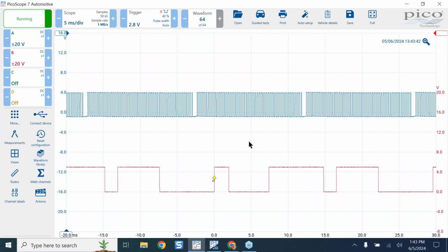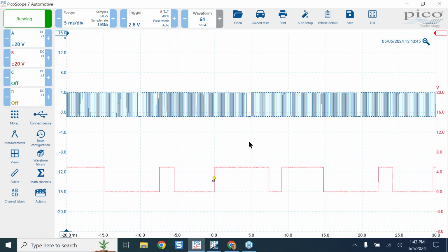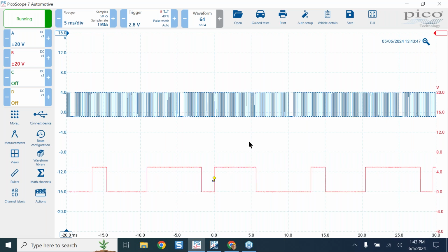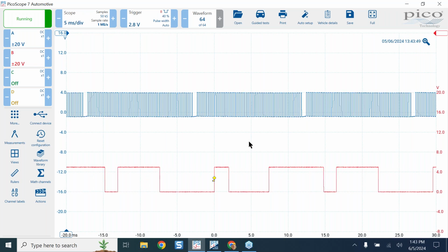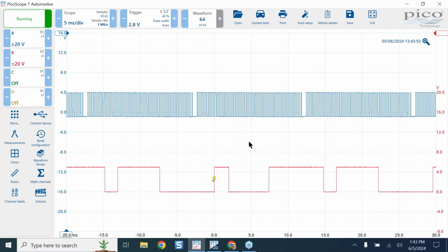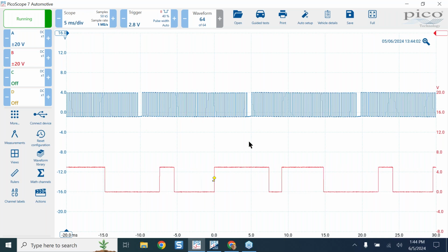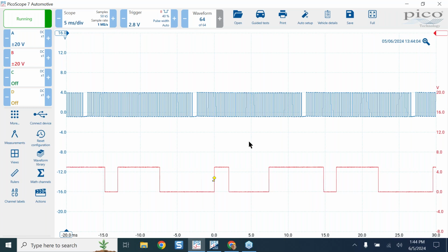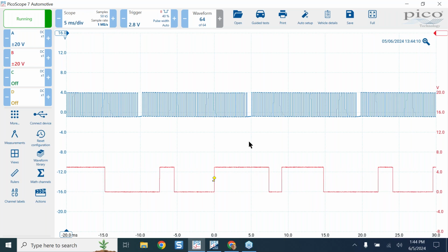But yes, using a COP on number one coil pack, or using a current clamp on the number one coil, not all the coils. You don't want to look at all 4, 6, or 8 ignition events. You'd want to just use one. So yes, going to coil pack is great. Typically I use COP. I'm typically going to use it on channel D because that's not a color that I see very well. So I will put it on channel D, move it out of my way, and then I can analyze my cam and crank.